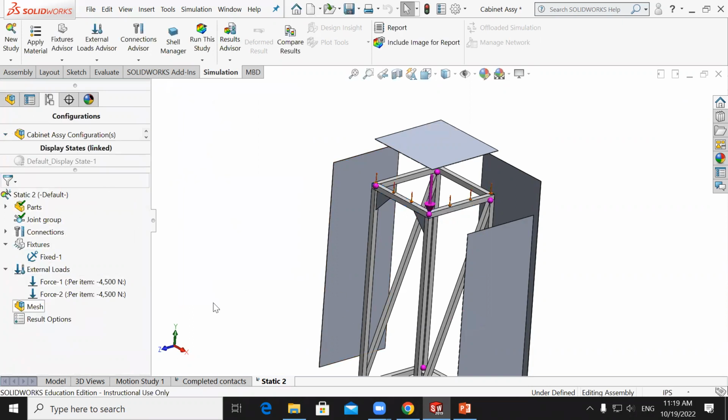And then we can create mesh, and then the same. If you would like to make the beam elements smaller, you can use the mesh control to adjust the element size of beam. But if you don't want, just let the program generate mesh automatically. Yeah, just say create mesh and Go.